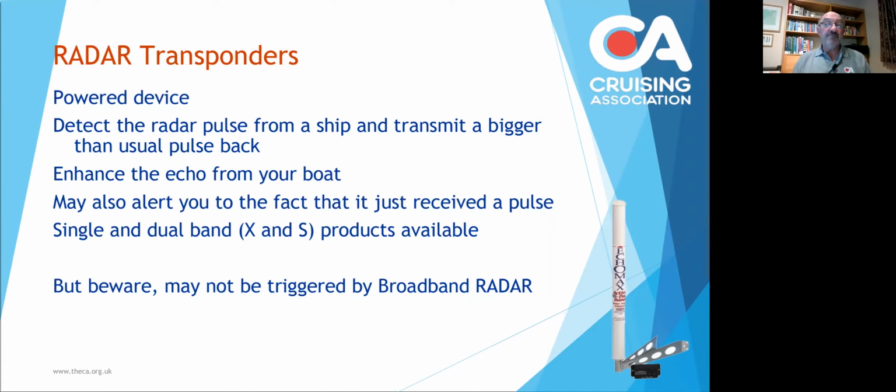So this is something particularly useful far out at sea, because it uses very little power, and at most of the time there'll be no ships about. But if you have that on and it gives a little bleep to say, I've just received a pulse, then somewhere within radar range is a big ship. Now you can get these in single or dual band products.